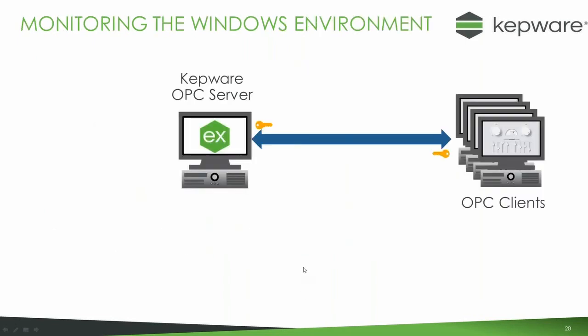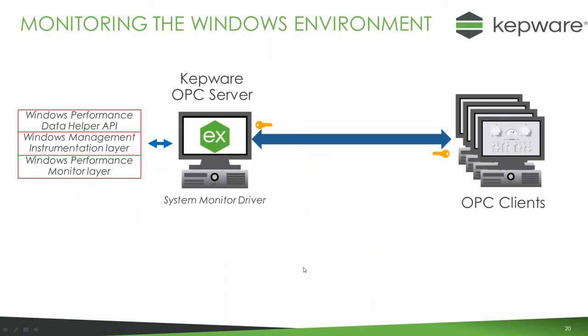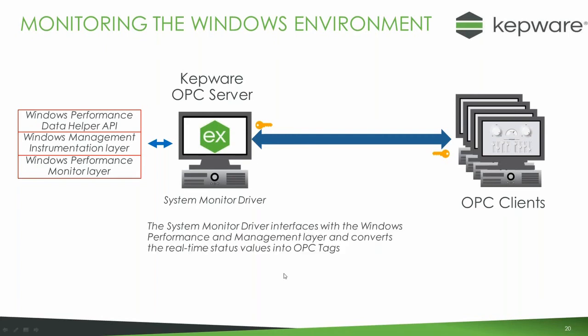Within KEPServer, there is a driver called the System Monitor driver. The System Monitor driver talks to a range of services provided by Windows, which are related to the performance and management of the system. This is within the Windows OS itself, and it's provided as standard. All that the System Monitor driver does is tap into that connection and provide all of the tags that would be inside the Windows performance layer or management layer out as OPC tags.